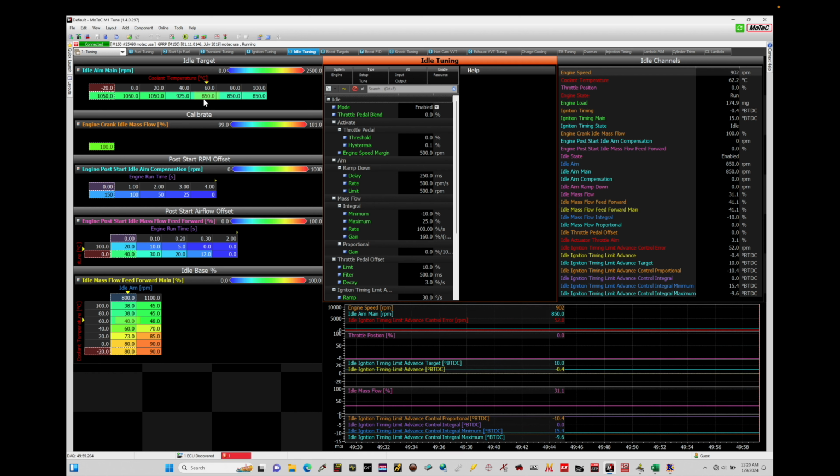We have a slow path and we have a fast path. Fast path is typically what we use, and in real time we speed up the control and vary the spark timing in idle conditions so that we have more of a fine adjustment on the engine's torque output to get us to the desired idle speed. And we utilize the airflow as a slow path of control in the torque output.